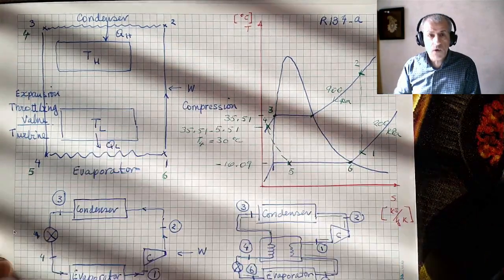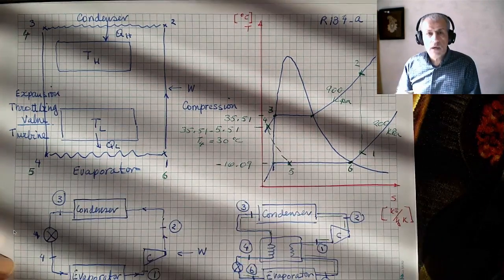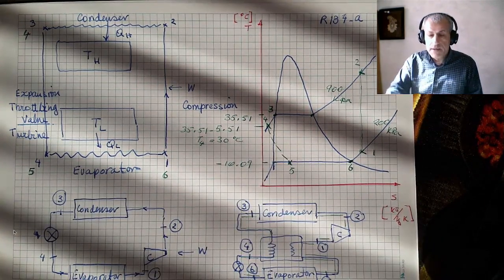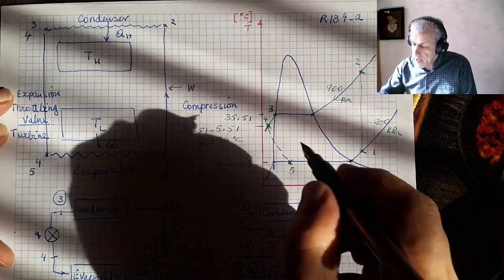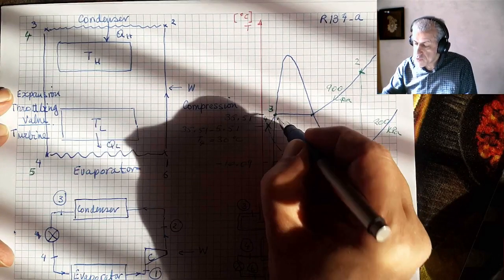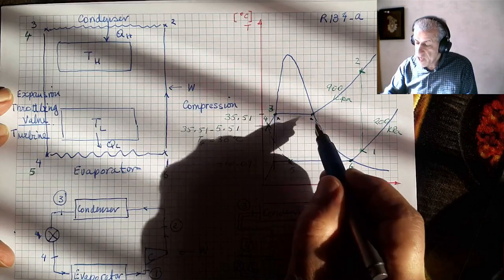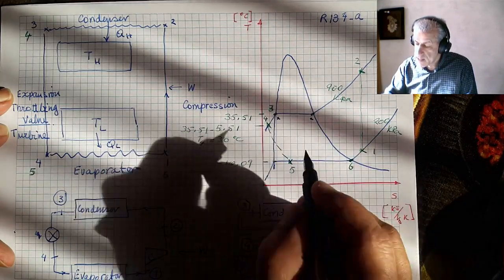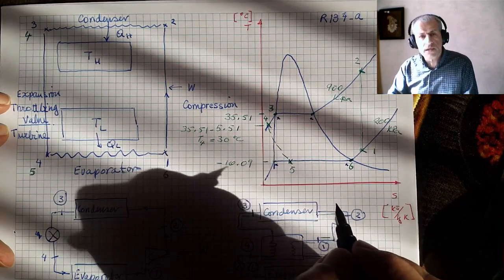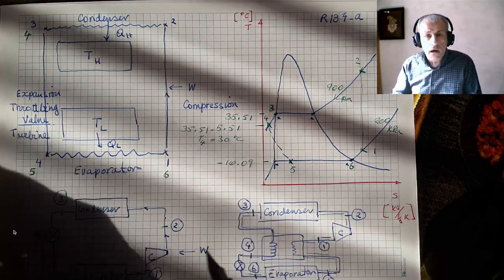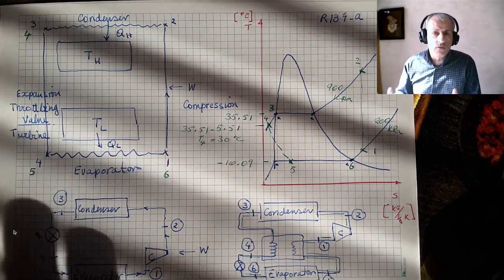point, okay, this point, and this point. So these are all the knowledge that I have copied on that table. So we have this point. I just put it with a cross, this point. This is HF, HG for 900 kilopascals, and this is HF and HG for 200 kilopascals. And these are all properties of R134a.